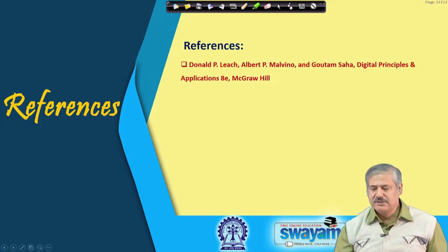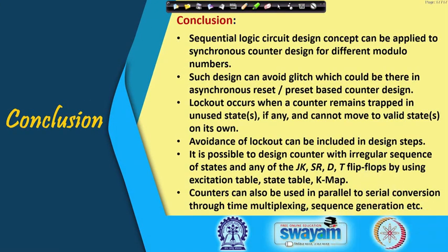So, with this we come to the conclusion. What we have understood is that the sequential logic circuit design concept can be applied to synchronous counter design for different modulo numbers, and such a design can avoid the glitch which otherwise is seen for asynchronous reset based counter design.